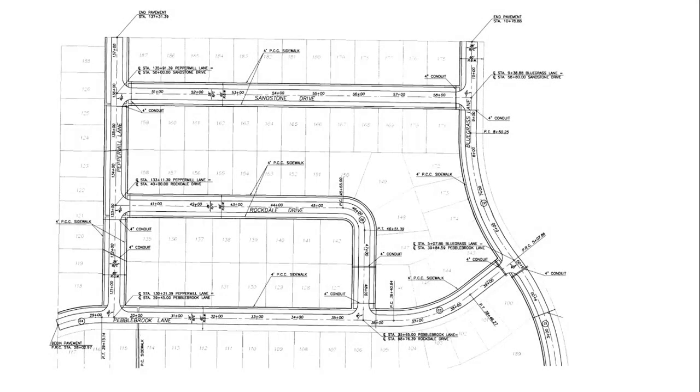Here you can see an overview of a subdivision with several side streets coming off of main lines, and as you can see, every street has its own unique stationing numbers. So the stationing on this street is 41, stationing down here is in the 30s, up in the 50s, and then at every intersection is going to be another station equation.